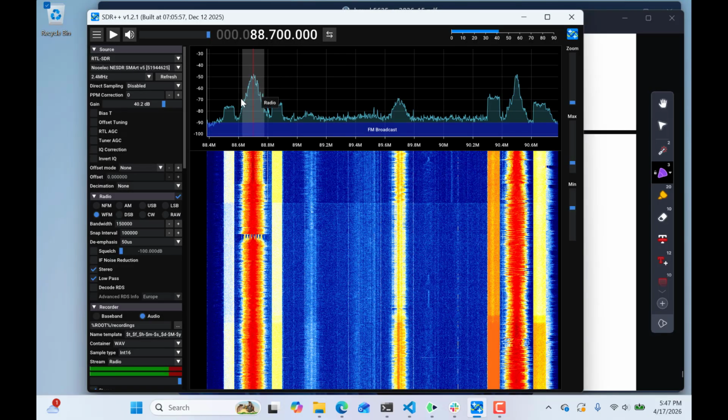This is FM stereo right inside of this blob. I can't see the subcarriers because I'm looking at it after it's gone through the FM modulator. So if you're looking to see the 19 kilohertz pilot and so on, you can't see it at this point. You have to FM demodulate this blob, and then you will see the left plus right at baseband, and you will see the 19 kilohertz pilot and the 38 kilohertz subcarrier.